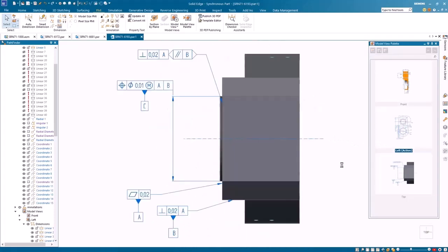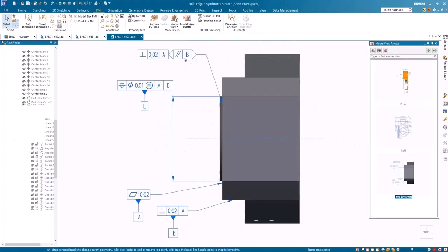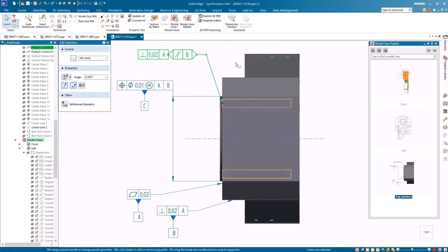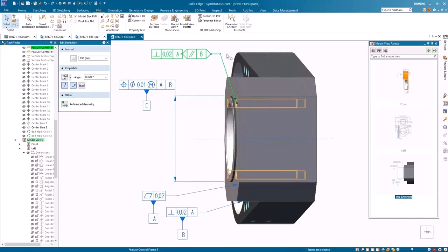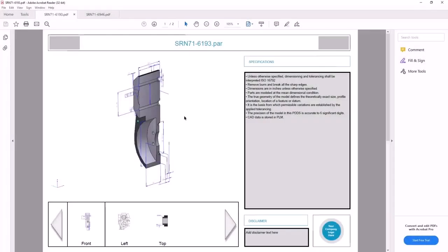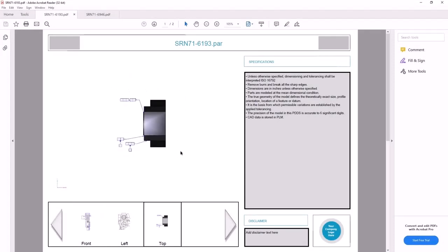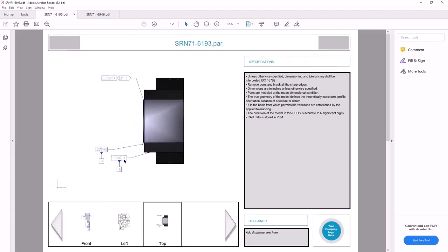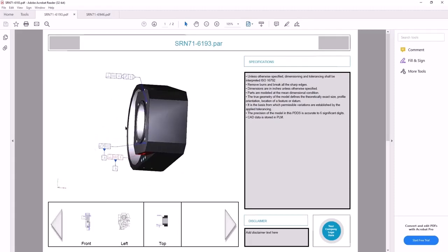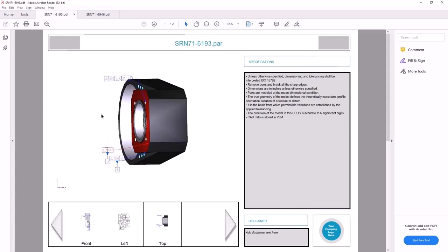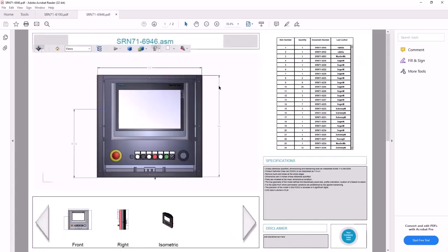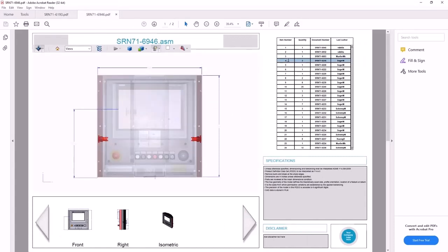Auxiliary plane indicators can be added, giving you more freedom to annotate the models based on ISO or DIN standards. Convey design intent for downstream manufacturing processes with 3D PDFs that can be published using templates. You can now export PMI views with selected section views and render styles to the 3D PDF, including those created with single planes, to streamline the delivery of relevant design information. With new PMI face association, parent faces and section views are automatically highlighted when they are selected in the 3D PDF.